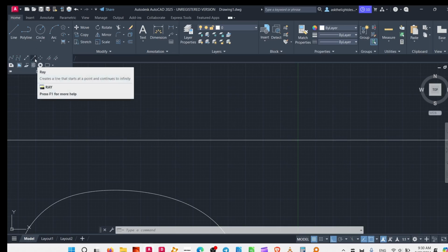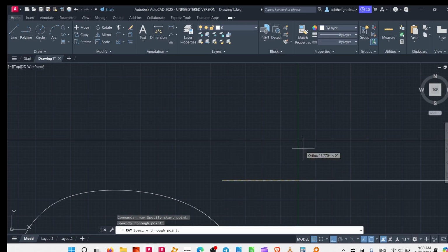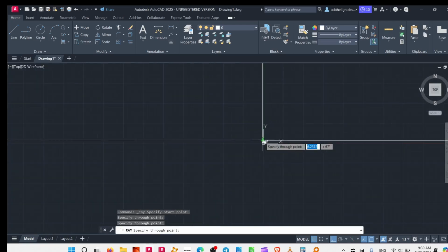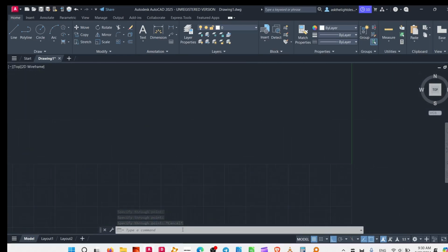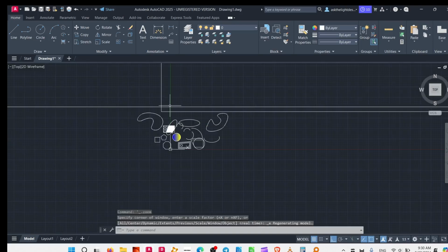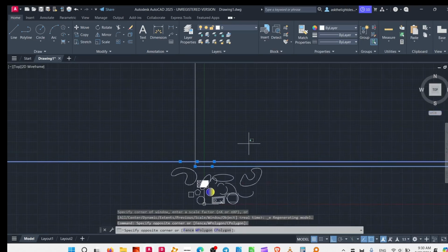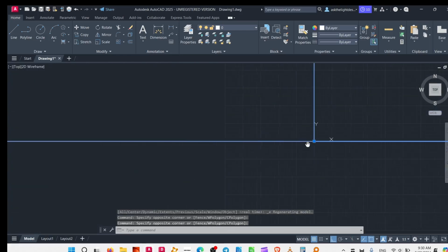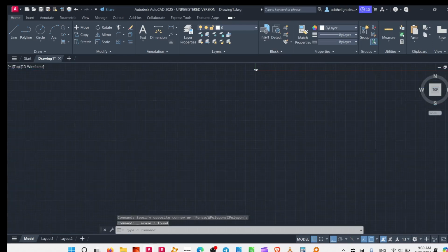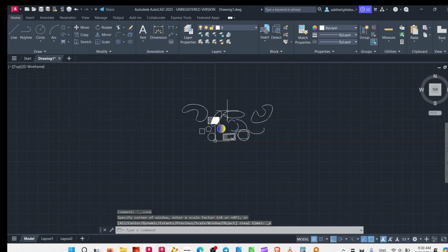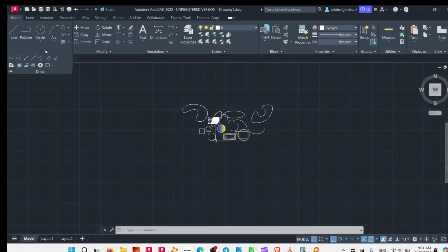This is a double-sided construction line, and this is a single-sided one, which is called a ray. So as you can see, the other lines are limited, generally in one area. These lines go across the complete drawing, all the way from end to end. I utilize it to create walls, for example, for buildings, and then I will use the trim command to close everything. And it is also what I use to align texts, for example.